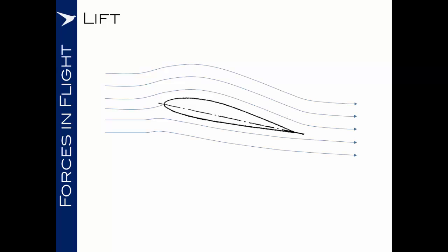So, how is lift generated? Well, the approaching airflow flows over the top and bottom surfaces of the wing. The wing acts as a venturi, causing a slight drop in pressure as the air is accelerated over the top surface and under the bottom surface of the wing. Versus the ambient pressure, the air pressure below the wing is at a slightly lower pressure, and above the wing is at a lower pressure still.